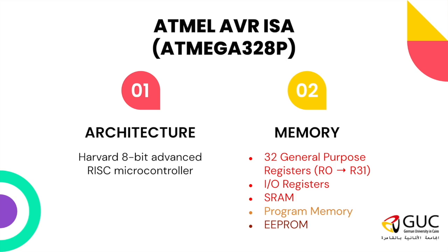These registers are the I/O registers, and they are used to control the different operations inside a microcontroller, whether I want to enable or disable such operations, or the bits inside these registers convey some information regarding the operations occurring. So they may be like flags. If you remember the zero flag from the computer architecture course in the MIPS pipeline datapath, the zero flag was a bit that conveyed that the arithmetic operation result was 0.